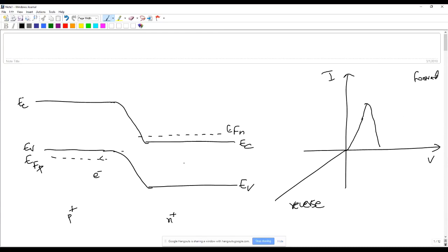So now I have a situation where tunneling is no longer possible because EC is above the valence band edge. So then your tunneling drops and then it reaches a minimum. But further conduction is still possible because your barrier height is also going on decreasing. Remember, this is V naught minus V external. So tunneling is no longer possible. So this region is basically where you have tunneling.